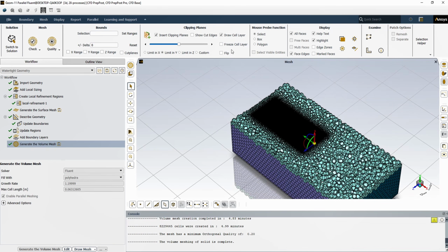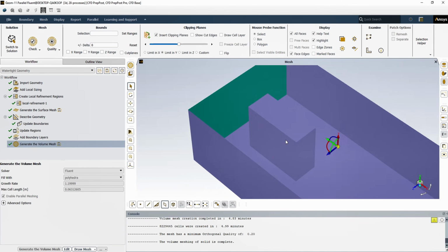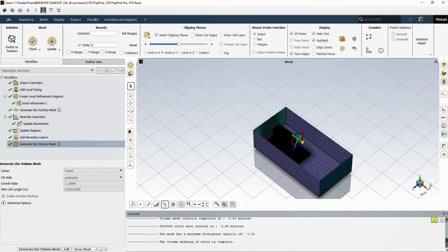This is because the settings you've configured for the refinement region ensure that a denser mesh is applied to capture more detail in areas of interest, such as around the smaller cube in your geometry. This local refinement is crucial for achieving precise simulation results where more detail is required.